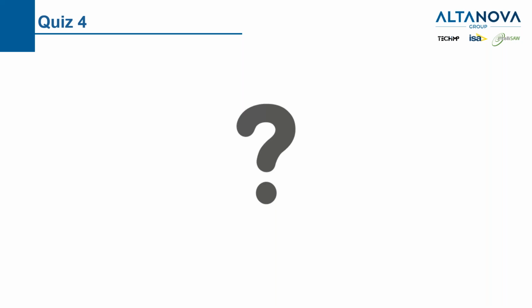Another question, what is your opinion for online PD measurement using RTD? In this case, when I see RTD, I think about the temperature sensor, but from my experience, I've never used such sensor for the PD testing, even because PD phenomena are spot problems. They don't normally give a big overheat of the stator. So the temperature is not the proper key to look at the PD argument.